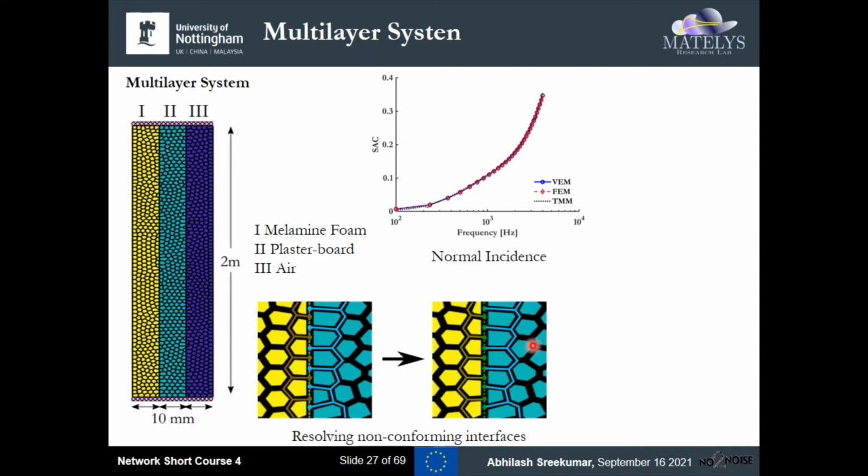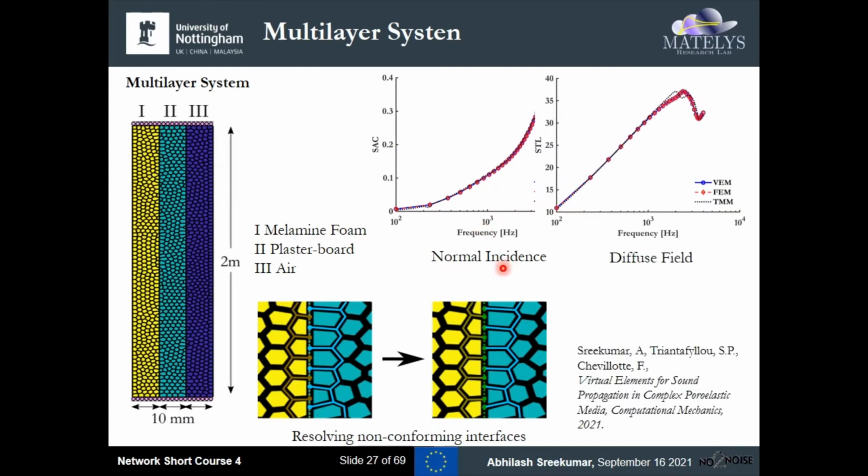This is the sound absorption coefficient obtained at normal incidence, and the sound transmission loss obtained at a diffuse field. You can see that the results between the virtual element, finite element, and transfer matrix method match reasonably well.